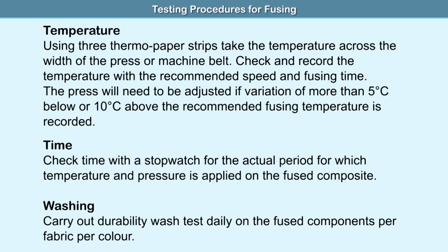The press will need to be adjusted if variation of more than 5 degrees Celsius below or 10 degrees Celsius above the recommended fusing temperature is recorded.